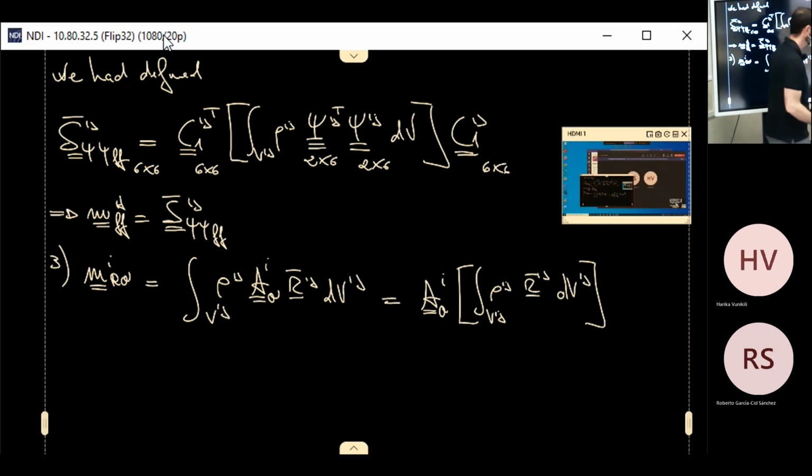So if we substitute everything, this becomes A theta I, which is applied over C2 Ij, the integral of the density Ij and Psi, because this is eventually the only term at the end of the game that depends on space, the element shape functions. And then you multiply it by C1, then you put it outside of the integral sign.